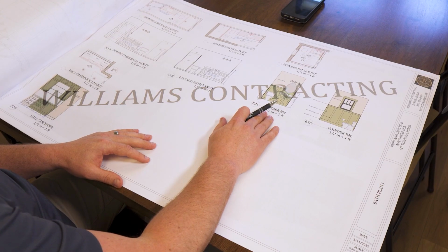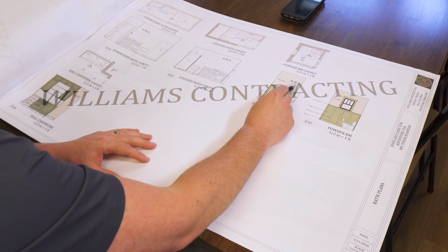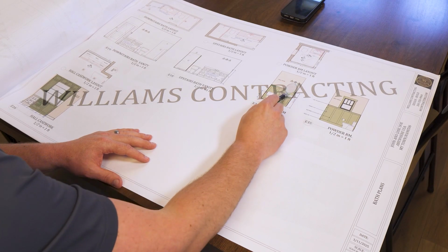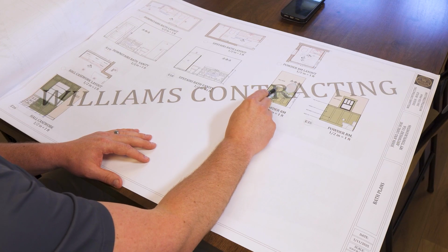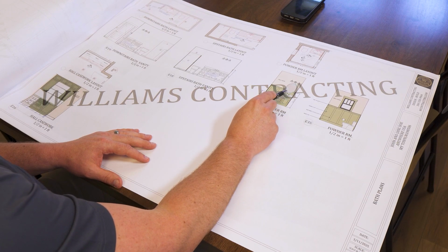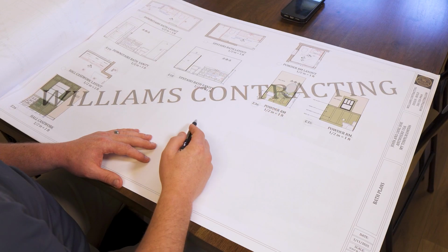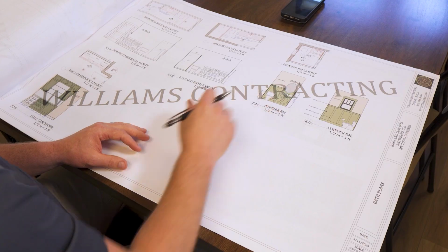Sometimes we can get hyper obsessed with everything being perfectly in line and symmetrical, and that's just not always possible. So visual references like this elevation here just communicate very clearly to you, from me as the builder, that we're not going to be able to line up all of our battens and everything with the mirror and the light and the vanity in a straight line, but the battens lay out symmetrically on the wall and the vanity is offset. I think this looks good, and it's not a big issue that they're offset in any way, but it does help to know it going in.